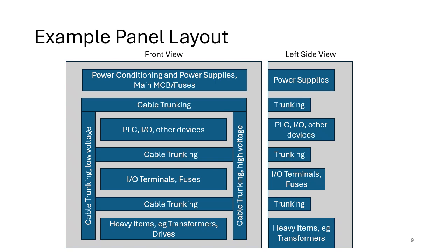And you also need to think about access around all of the devices. Is there actually physical space to get your fingers in to do the wiring? Is there space for expansion? And is there space for heat dissipation, which will come from the vendor's instructions? So there's quite a few considerations as to how we actually build this panel layout.